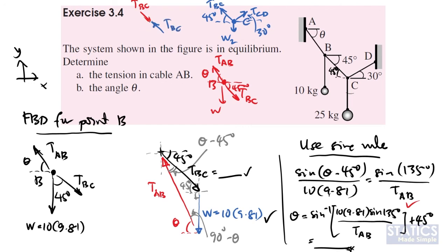Since both of these forces have the same magnitude along the same line of action but in opposite directions, the sum of them is 0. The sum of the forces is 0, so that means this point here will be in equilibrium. Make sense? Yes, sir. This is another way to check whether your free body diagram is correct or not, especially between adjacent points.